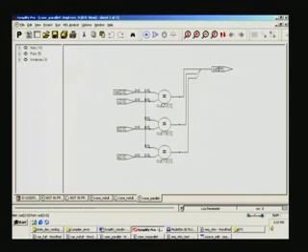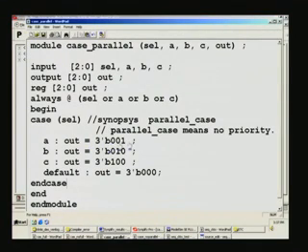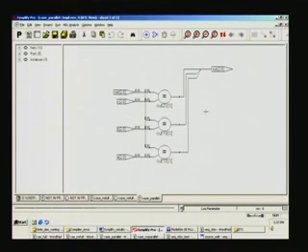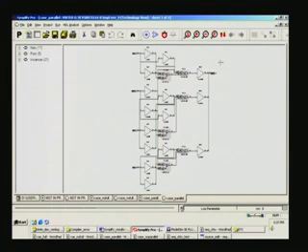So that is governed by the code that you have already written, that is here, right. This is not plain there, and so is the case for select equal to B, select equal to A. So it is primarily this, and this is the technology view. Once again you see all the inputs have I buffer, and then outputs O buffer, and then you see LUTs being used here, 1, 2, 4, 6 LUTs are used. Once again these are all input buffers, and this is a parallel case.